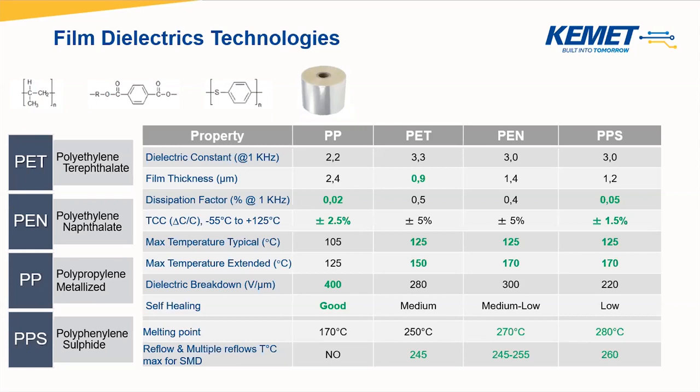So this means that I can use this capacitor in designs where I want to apply a high electric field. We remember from the previous formula that the electric field is given by the ratio between the voltage applied and the thickness of the dielectric. So it means that working at a very high condition of volts per micron, I can increase the energy density of the capacitor.